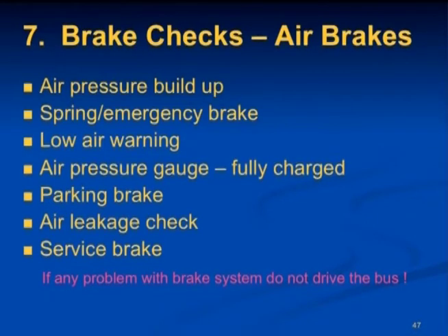Continue to build the pressure until the system is fully charged, which is around 100 to 125 psi. You can hear the cutout at about 125 psi. If you have air brakes and you do not pump down the brakes as part of your post-trip inspection, you will reverse this procedure by pumping down for each test.